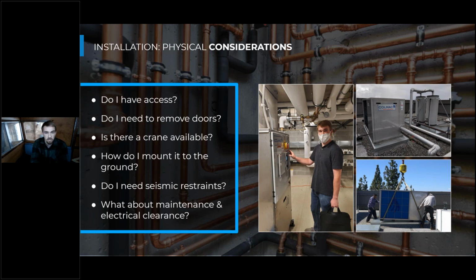And when it comes to crane scheduling, you do want to follow up with the heat pump manufacturers to keep up to date on the lead times that you'll see with this equipment. If lead times change and your crane is scheduled to be done operating by the time the heat pumps actually arrive, then the crane's not going to be helpful for that installation, and you're going to have a hard time recouping the cost of the crane itself from the manufacturers or reps.